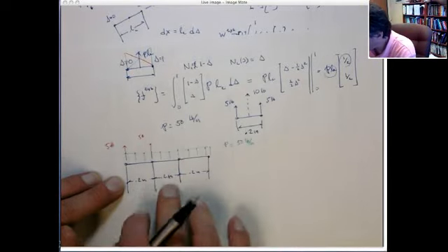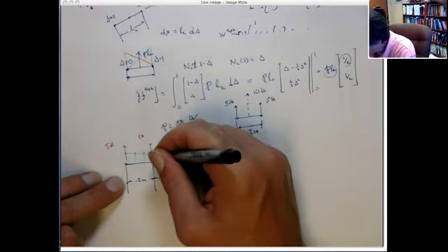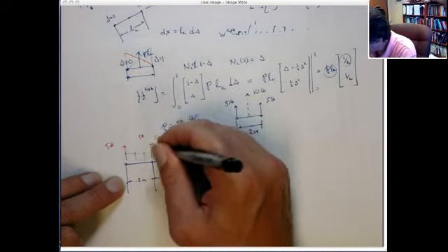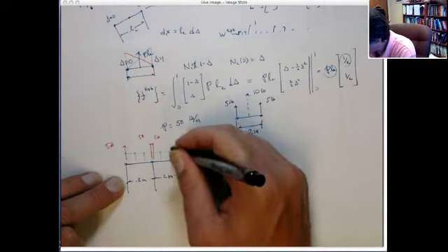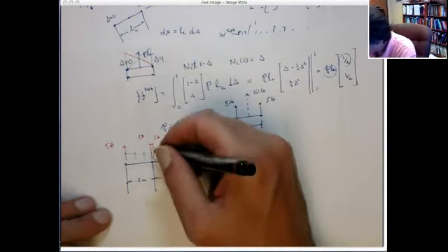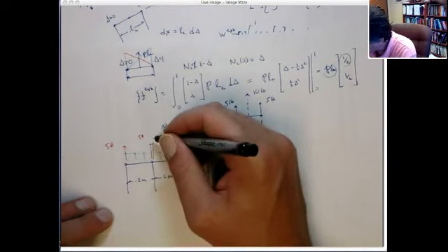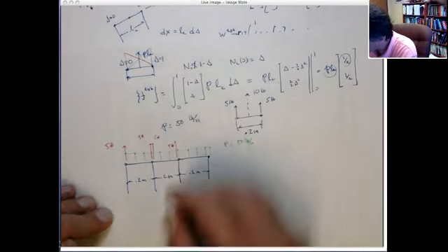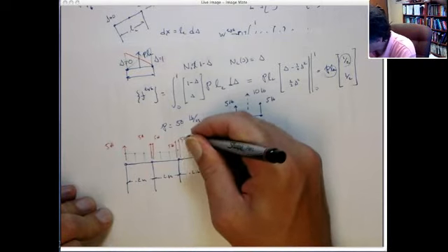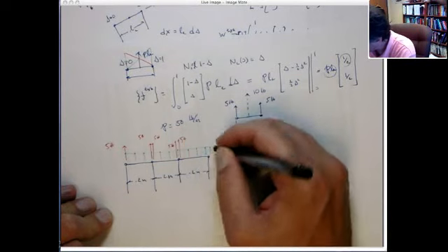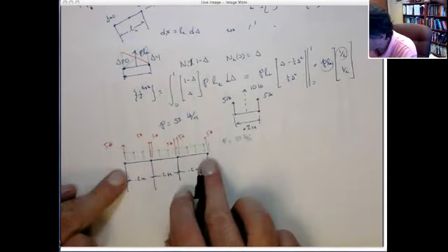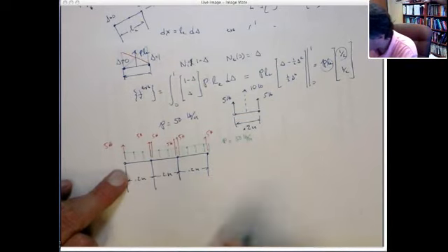All right, then we move to the next element. This would contribute another 5 pounds to this node, and then 5 pounds to this node. So actually, at this node, the actual force you're applying here is the sum of these two, so it's 10 pounds. And likewise on this node, we put another 5 pounds here from this element, and then the 5 pounds on this edge. Now, since these two outer nodes don't have any other elements next to them, they're going to stay at 5 pounds.